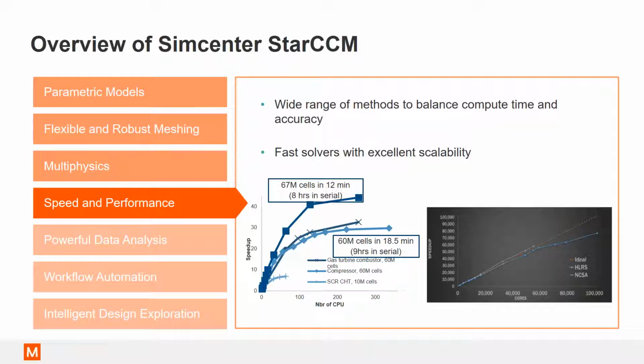It did exist 2 years ago, but due to the acquisition of CD-adapco and Star CCM Plus by Siemens, that connection no longer exists. But Star CCM Plus has a Parasolid kernel, and it is the same kernel that's used for SolidWorks. So there is no loss of data when importing a SolidWorks part into Star CCM Plus.